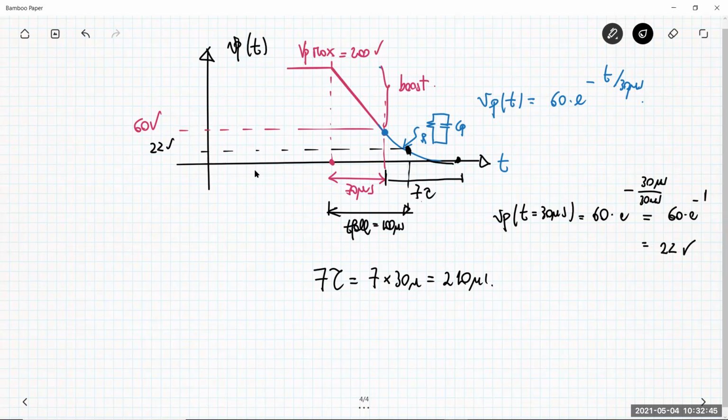So this, if you want, is a drawback, okay? Because I want to respect very precisely the timing constraints that my injection computers give to the injector systems. But in this case, I have to wait for the discharging phase, an exponential phase that is a little bit longer. Then there is another drawback in doing this kind of dissipation. Let me consider, for example, the power which is dissipated by this resistor.